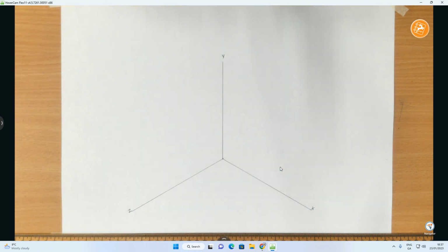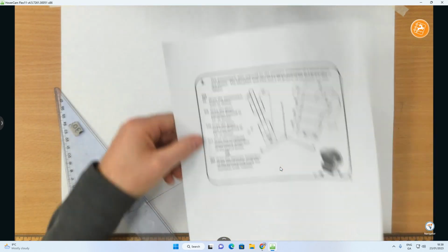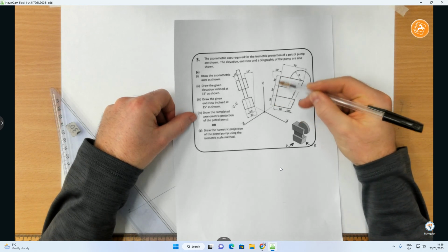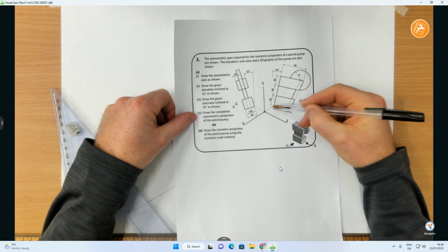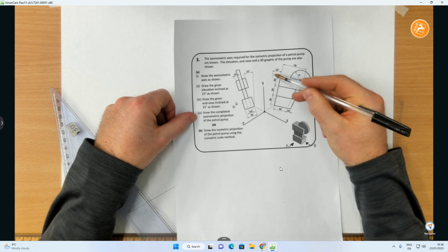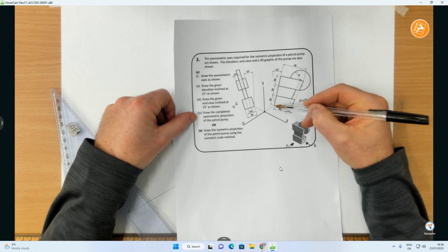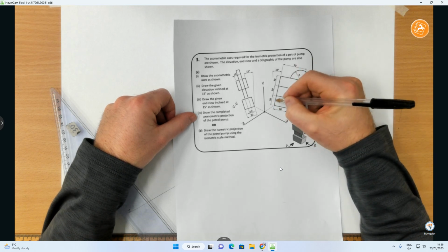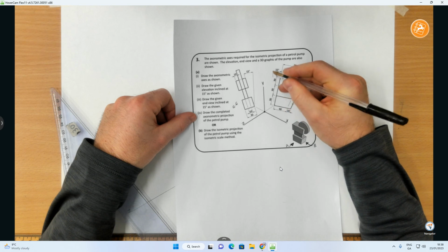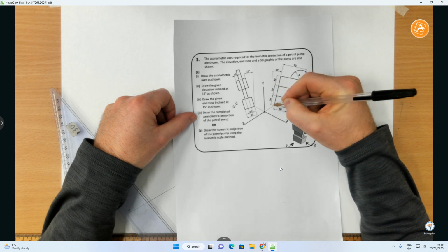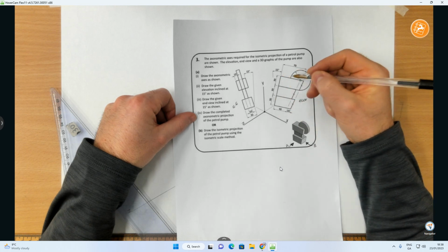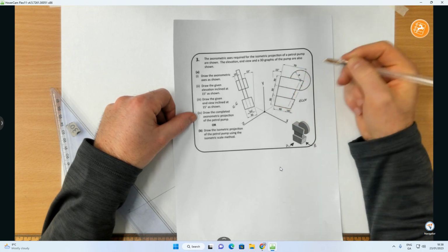Now what I want to do is set up these 90 degree lines here, where this one, as you can see, is inclined at 15 degrees, and this one here is perpendicular to it, so it's going down at 15 degrees. But really that line there, if we take 15 away from the vertical line, which might be inclined at 90, let's say 90 minus 15, that line is at 75 degrees. So we're going to use a little method there to get that line and then this line as well.